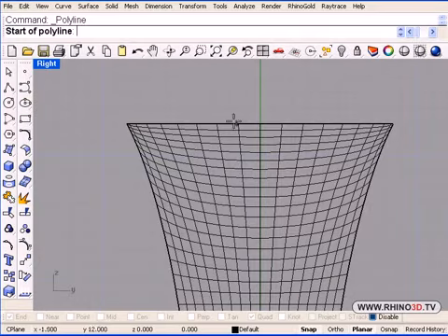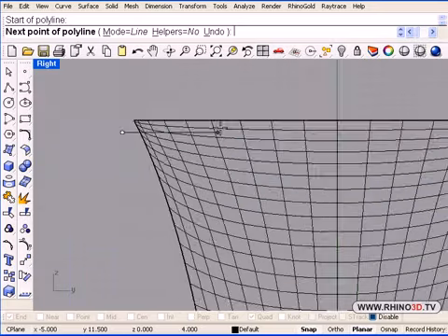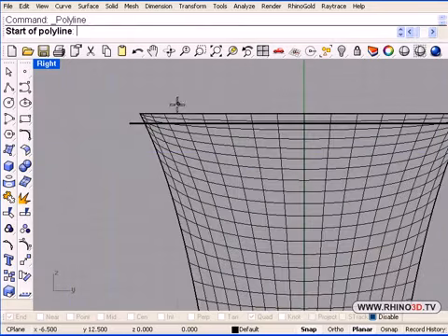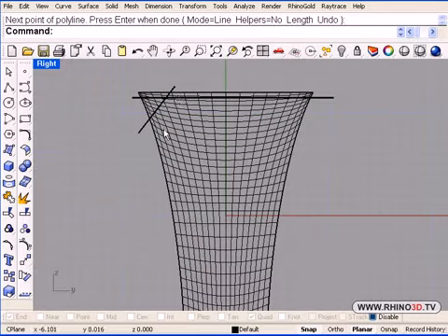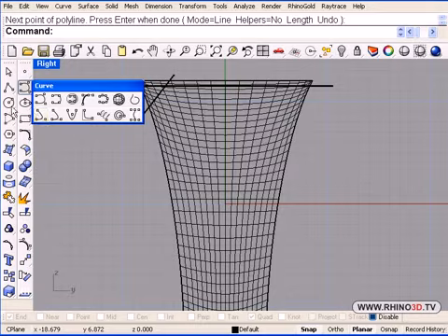This time you can get creative and do whatever design it is you're putting on the side of the ring. Just make sure as you're drawing that you give yourself the right clearances. Don't get too close. Don't make things too small that later on machines cannot reproduce it. So make sure you know the specs of the manufacturing process so that you don't make something too small.